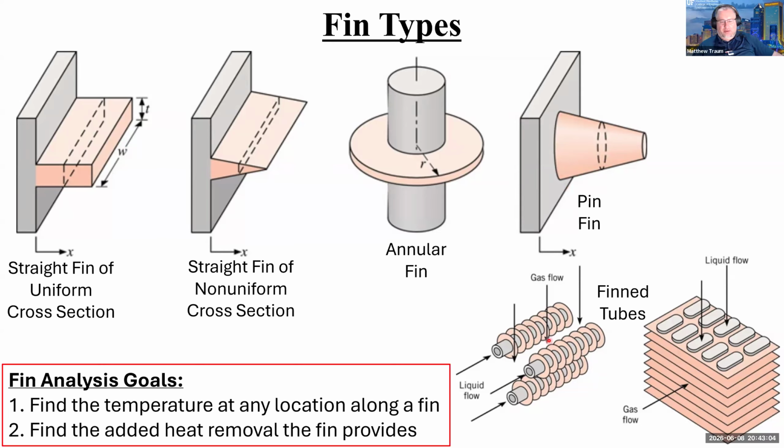And then we also have different types of finned tubes. When we were talking with Sandvik, we were talking about their oil cooler and the fact that you would run hot oil, so liquid flow, through these hollow tubes, and then you would have some sort of collar, like a welded add-on annular fin, on the outside of the tube. Then with the fan, remember they were talking about that big fan, you blow force-convected air over the fins and exchange heat with the liquid that way.